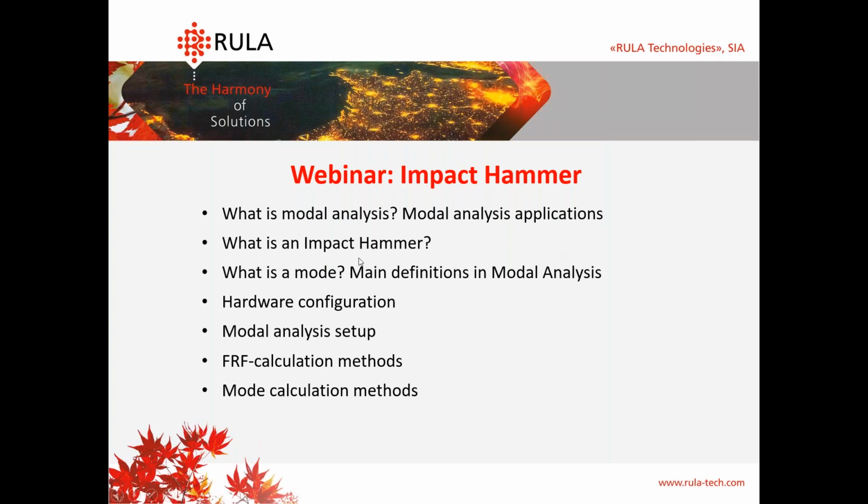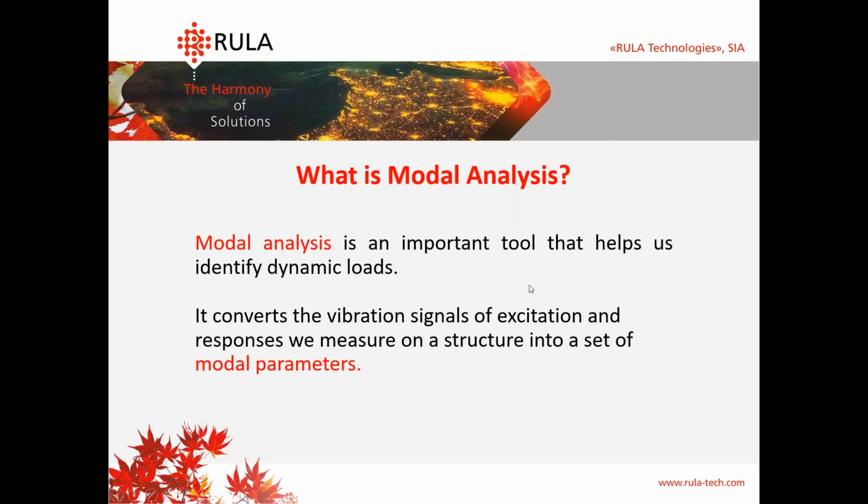I will talk a little bit about the impact hammer, and discuss modes and main definitions for modal analysis. After that, we will discuss today's setup and configuration and perform modal analysis using impact hammer and stepped sine sweep.